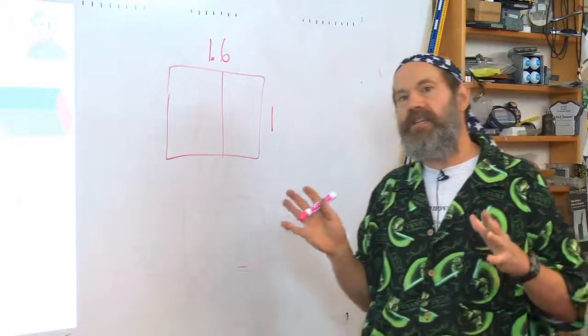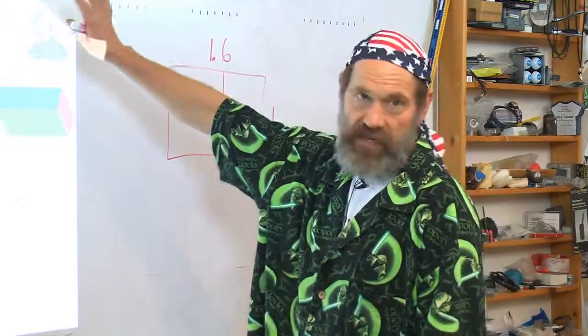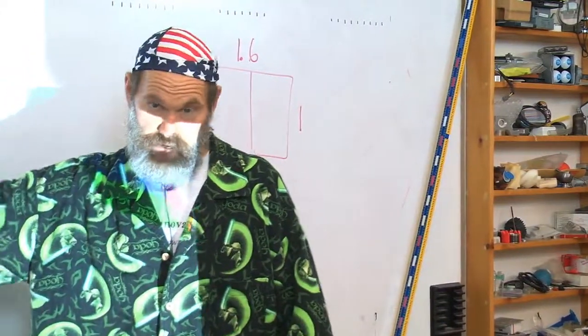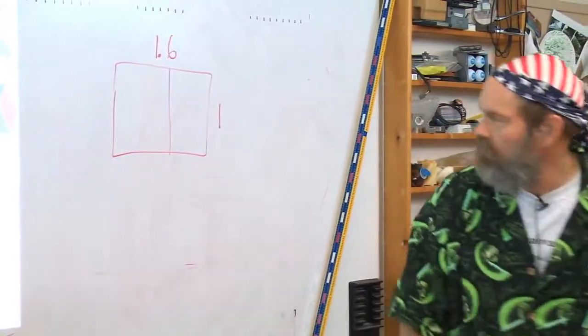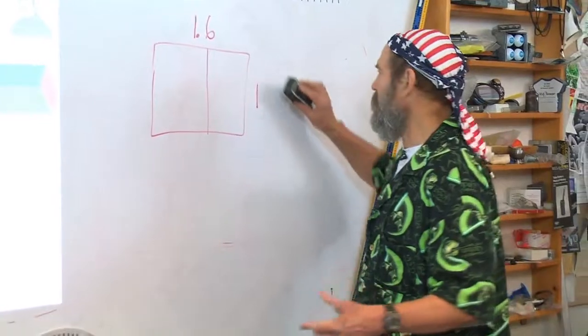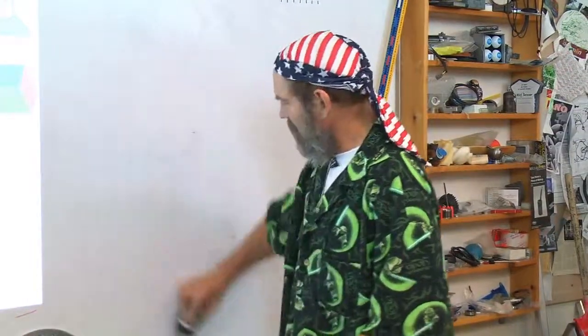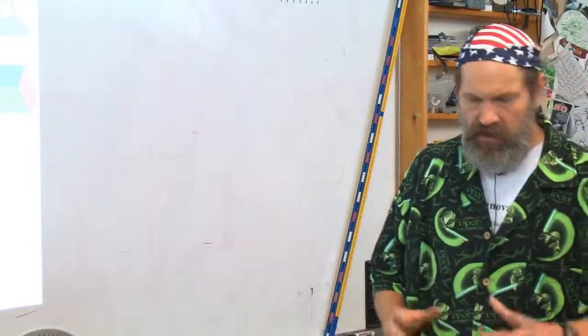So when I'm laying out a design, and you can get the golden spiral, all kinds of cool stuff out of this that you'll learn from Donald, when I'm initially laying out a machine, what proportions do I use for things? And tying back into St. Venant's principle, we said if you want to control something, grab it by 3 to 5 characteristic dimensions. Can it be 2? Can it be 1? 1 is often pushing it unless you have really low friction.